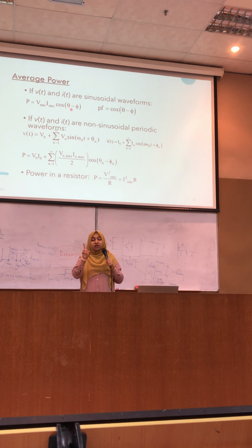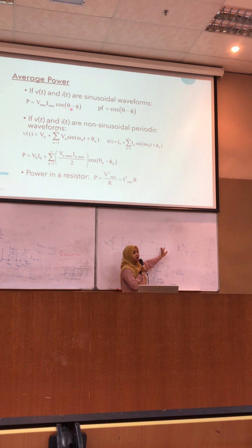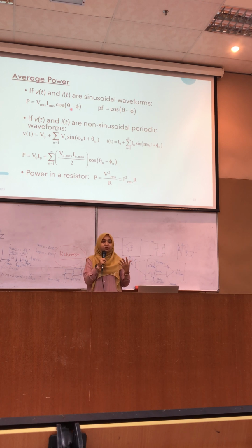And if you see from the oscilloscope or from your simulation plot, the voltage and current will not be in phase. In phase means the signals start and end together. If the waveforms are not in phase, where one ends before or after the other, it will be a leading or lagging power factor. So it depends on the value of the inductor or capacitor inside your load, how high the value of your inductor and your capacitor.